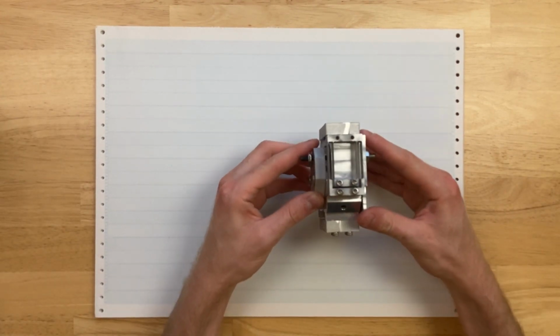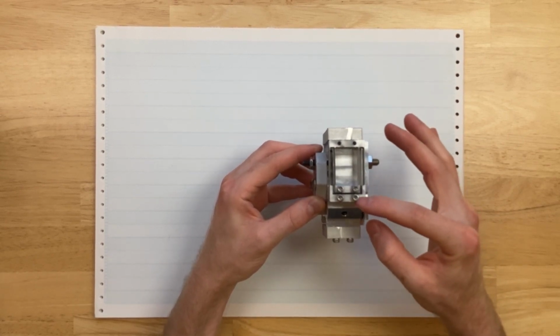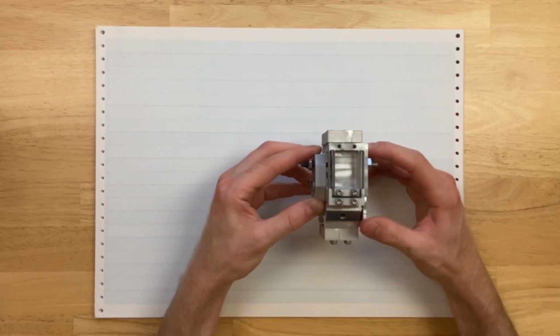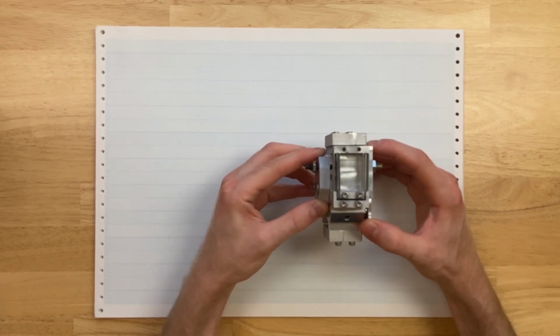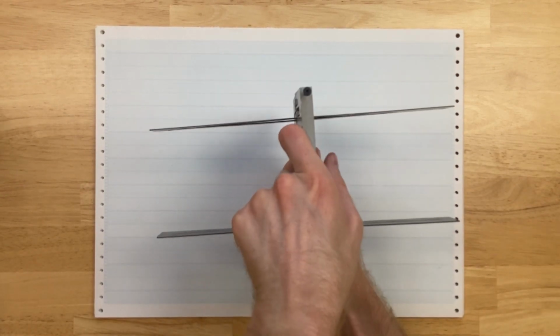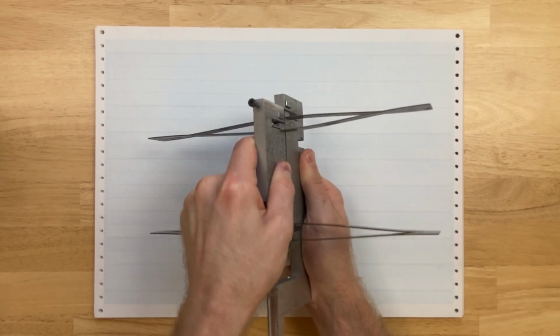You can even take this further and make double parallelogram flexures, where as this stage moves relative to that fixed base, this intermediate stage moves half as much. This helps take out some of the parasitic errors and gives you more range of motion, otherwise changes some of your stiffnesses. You can even take it to the extremes and make systems that have two flexural supports and exhibit very large ranges of motion, even if they don't have the traditional parallelogram setup.